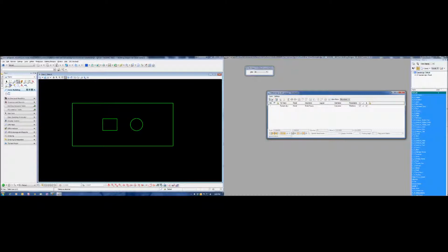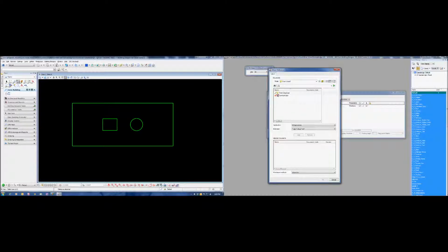So at this point we can attach the border and the CS design file. So we're going to go Tools, Attach again. We're going to go find our border in our project. And we can add it so we can go find our CS design file also.